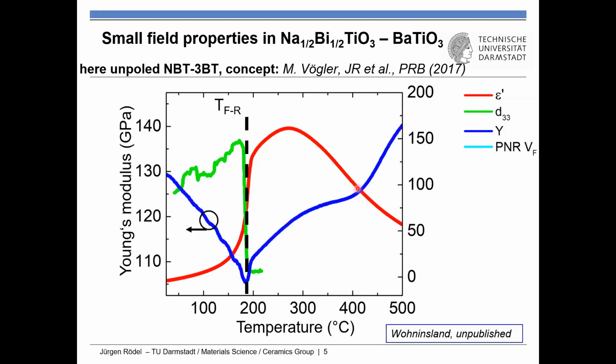So let's plot the Young's modulus. Now that looks quite different from barium titanate. So down here, this is actually pretty linear. In a single phase material, it's supposed to go linear down with temperature. Apparently here, we don't even have a single phase material yet. It's about here.